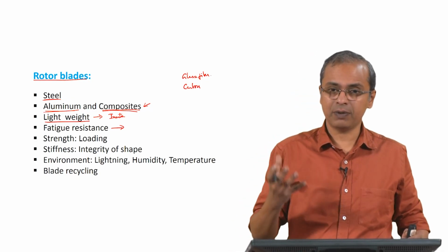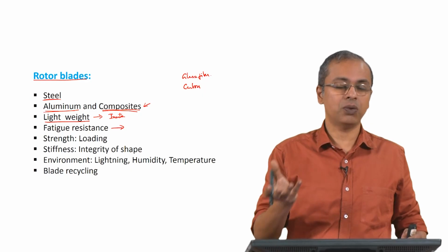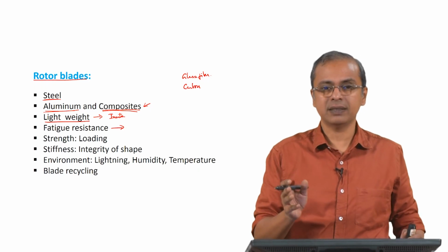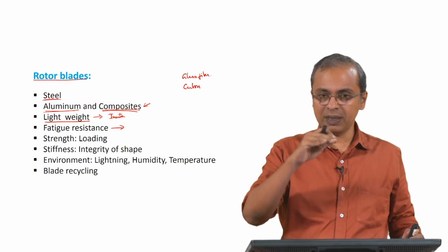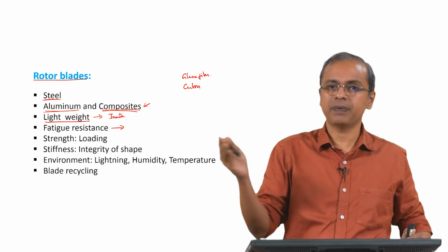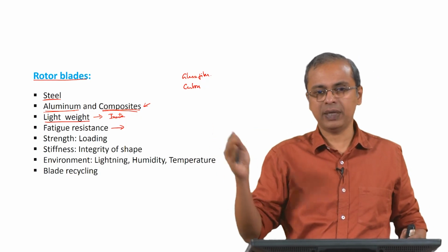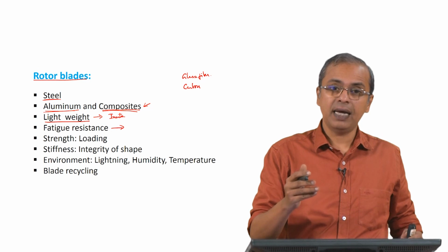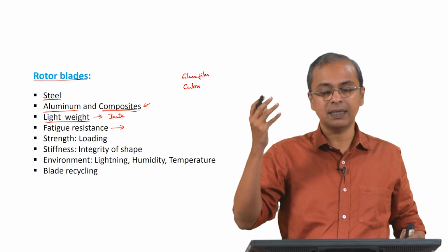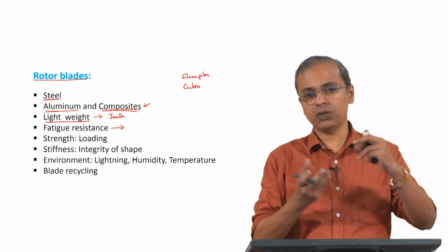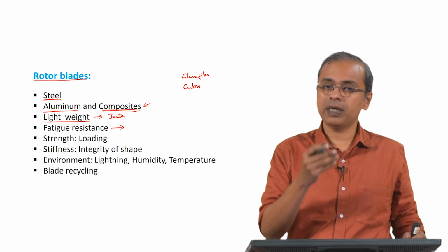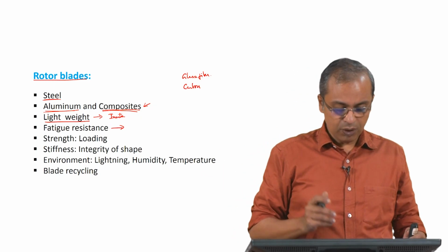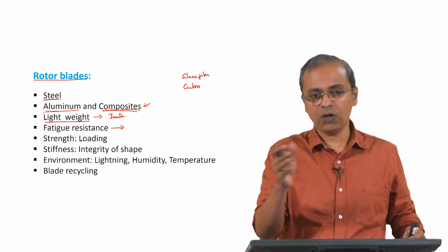So, people test to see if materials will fail under such cyclic loading conditions. It is generally found that a vast set of materials, when put through cyclic loading, and in a systematic test you use a known frequency and known load level, will fail at a value of stress significantly lower than the rated stress of that material. You did the original test and came up with some value, but under cyclic loading, even though you are loading it with much less load, just because it is cycling repeatedly over a long period of time, it fails. This phenomenon is called fatigue.